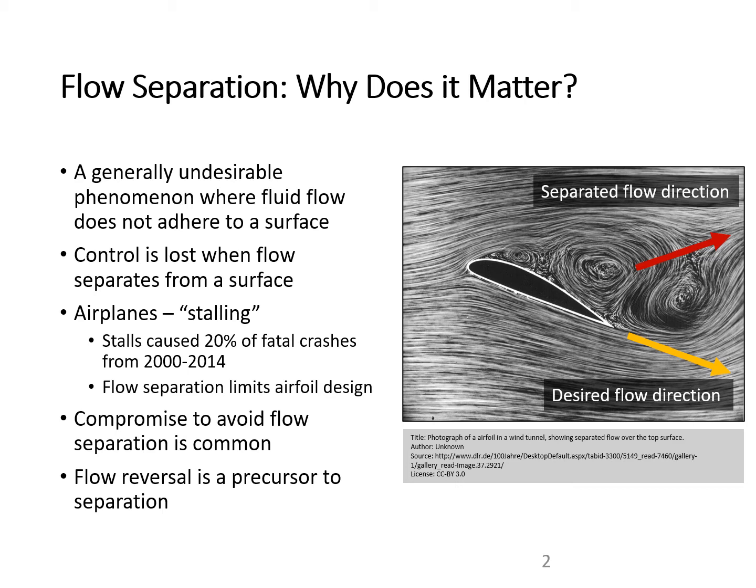The airfoil should be producing lift by moving the air downward, but instead it's producing negative lift by moving that air upward. In airplanes, this phenomenon is known as stalling, and it's a big deal. Stalls caused about 20% of all fatal crashes that occurred from 2000 to 2014.